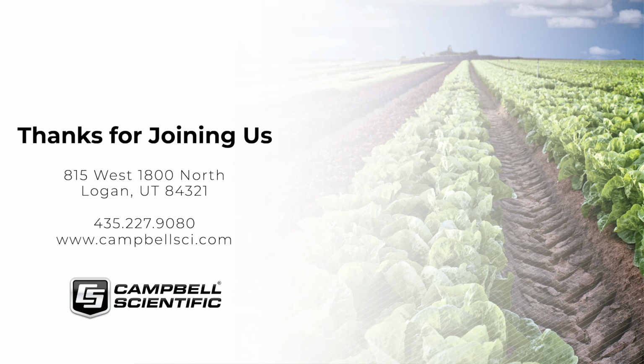Jason, I think you're right with what you just mentioned there. There are limitations to the reflectometers, which are like the 616, 655. Absolutely, TDR is going to be able to overcome some of those challenges, textural or maybe high EC or temperature effects, a little better. I think the added measurements that are given from the CS655, conductivity and temperature, can really help to develop your own soil-specific calibration. So that might be something to look into.